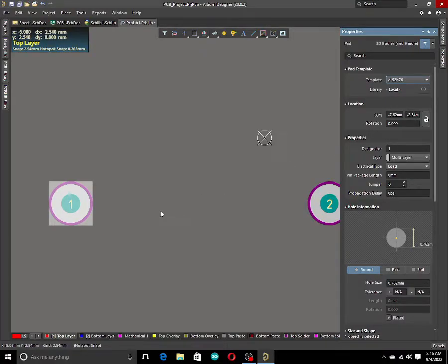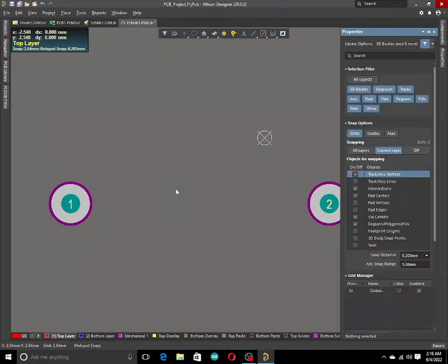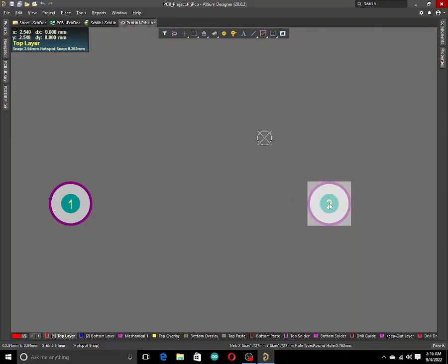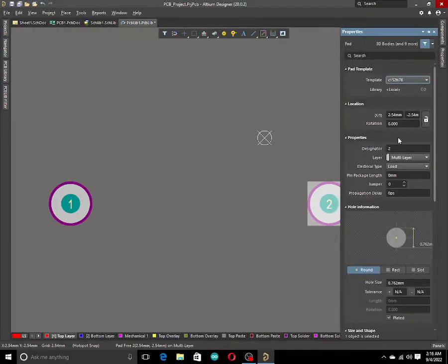We are changing the X position of the vias. So minus 7.62, we need to make a shift, and the other holes are spaced from center to center by 10 mm. So minus 7.62 plus 10 mm is, I think, 3.62. You just write 3.62.